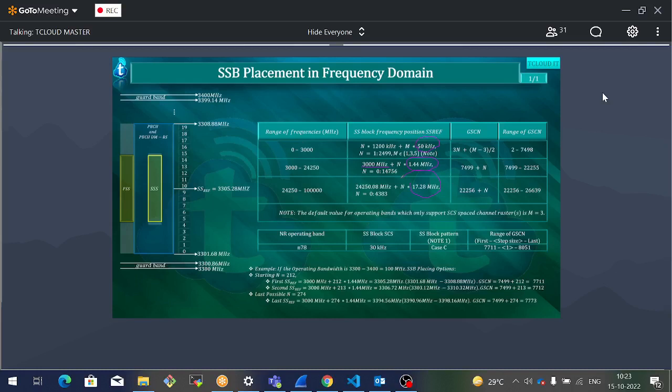So how much amount of band you will download and decode into symbols to search for PSS symbols? That is what is giving you that point there. So I put down some kind of a calculation. If we start with the 3300 megahertz band, there is some guard band up to 3300.86 megahertz, or 860 kilohertz, that you leave out.